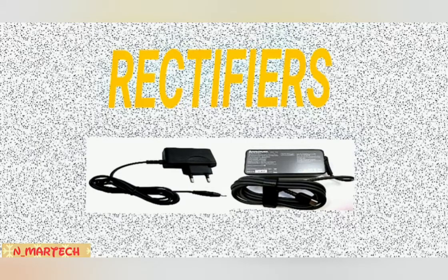Rectifier circuits. These are used in power electronics to convert alternating current to direct current to be used by DC loads. This is possible due to the presence of certain components in such circuits. These components are diodes or thyristors. They do the main rectification. Other components like transformers, capacitors, resistors etc. perform secondary, although vital roles in the rectifier circuits.